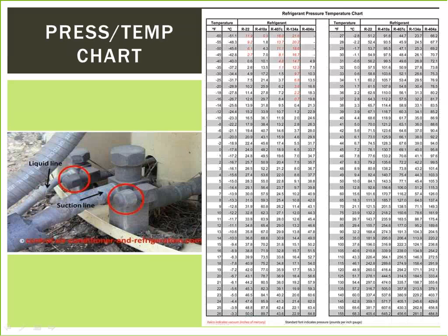If we accept 40 degrees Fahrenheit as a desired evaporator temperature, an R22 system's normal low side pressure will run around 68 to 70 psi. For R410A, it should be around 115 to 120 psi. As for high side pressures related to R22, you're looking for a pressure that is about 20 degrees Fahrenheit above the ambient air that is entering the condenser.